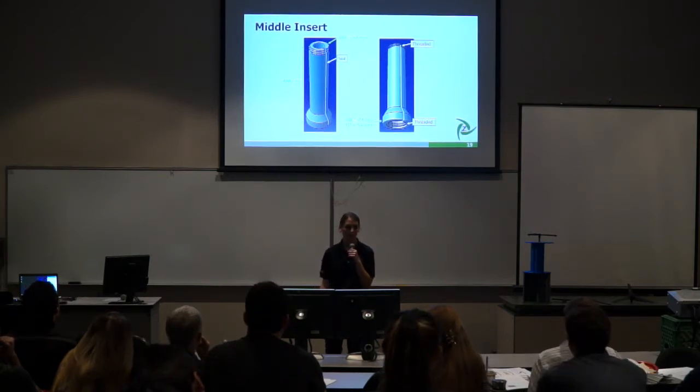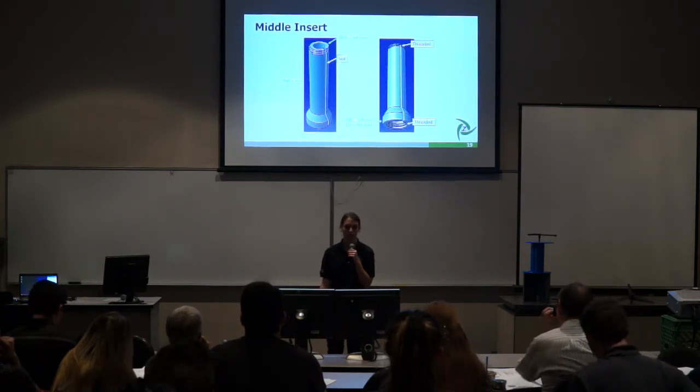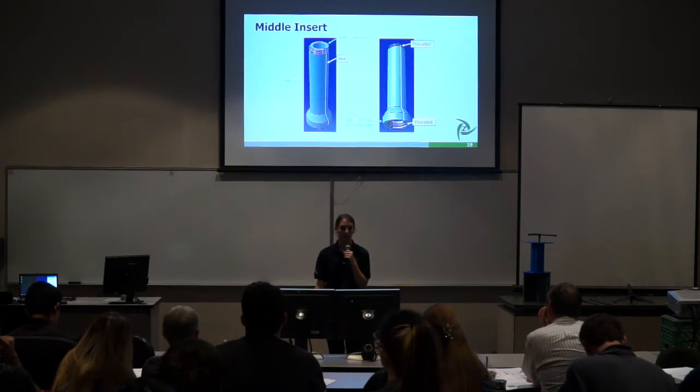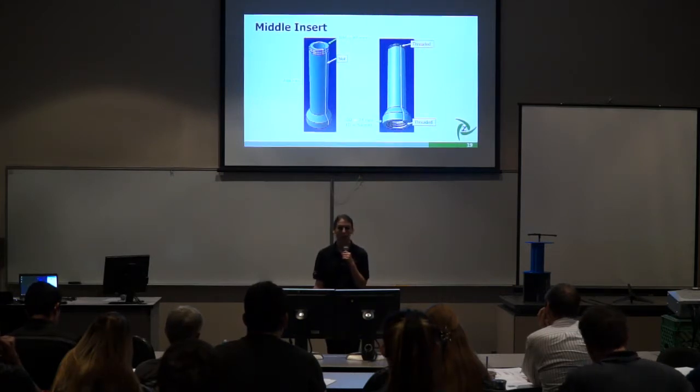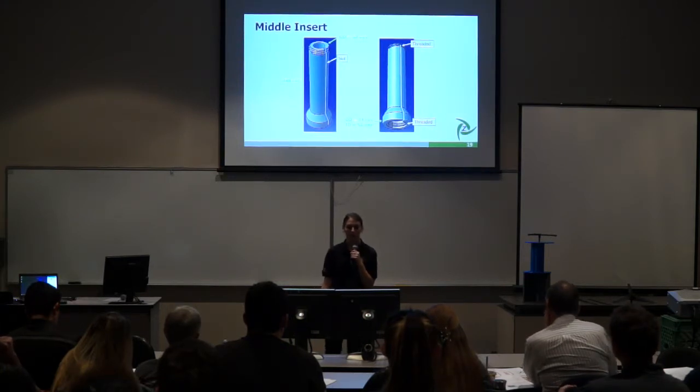There is a slot on the side of this piece to allow for the wires to go inside of the structure while in use. To clarify, the motor will be housed above the middle insert and the electrical components will be housed below the middle insert. This slot will allow for ease of transition going from the VOT to the HOT so that no wires have to be disconnected. The top and bottom of this piece are threaded to allow for connection to the top base and the bottom base lid.